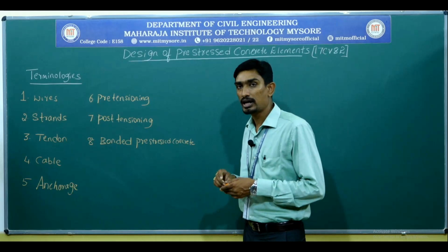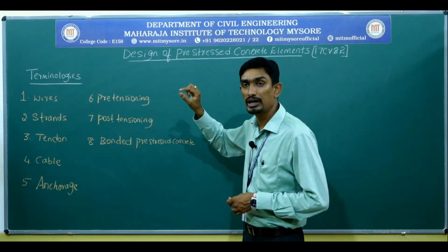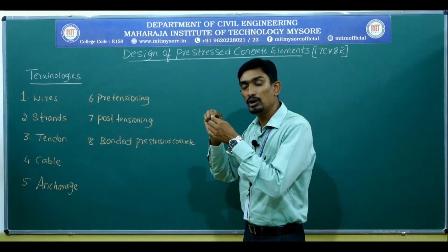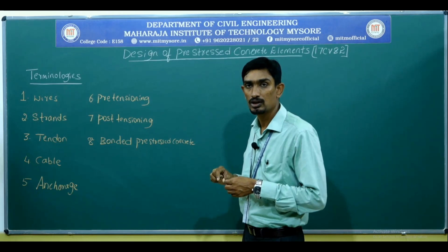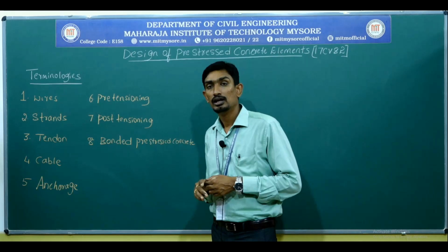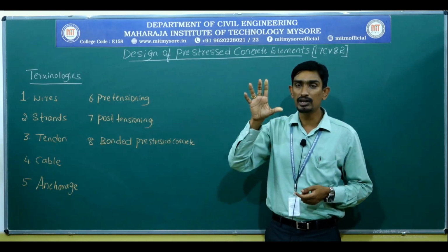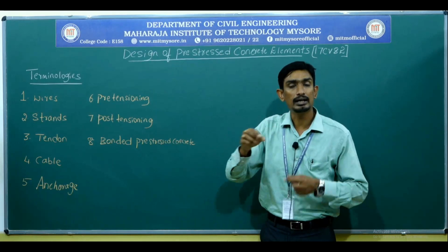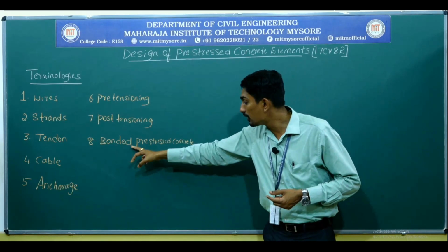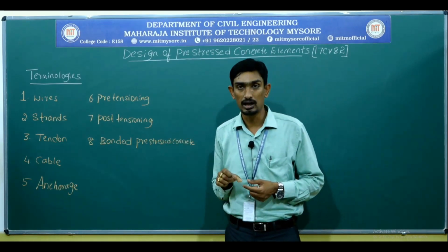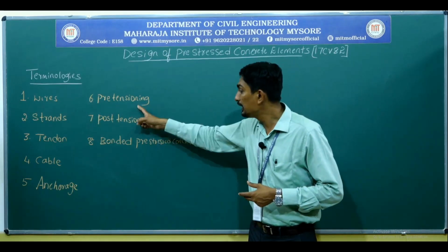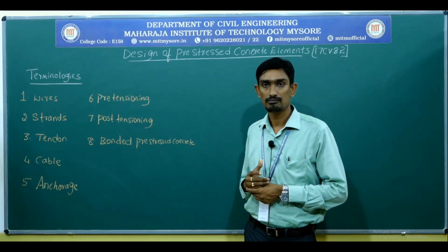Whatever tendon I induce inside, I do the pretensioning, and afterwards I put the concrete. That means the bonding between the concrete pour and the stretched tendon makes the bonded PSC. The stronger the bonding, the better will be the behavior of pretensioned beams.